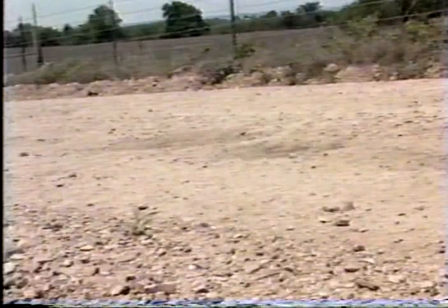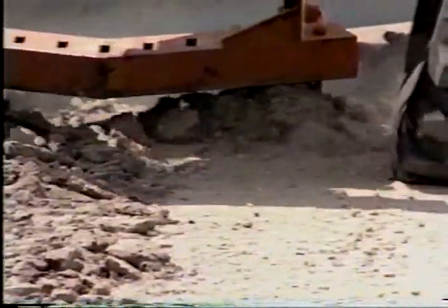If the surface is too hard to blade easily or the trouble spots too deep, scarifying is necessary. The main point to remember in scarifying operations is to cut only as deep as necessary, usually only 2 or 3 inches. The scarifier should cut to the bottom of the pothole or ridge, leaving as much existing crust as possible. Once the area has been scarified, the material should be remixed in the same manner as reshaping. Scarifying can be effectively used to reshape small sections of roads that may otherwise need only smoothing.